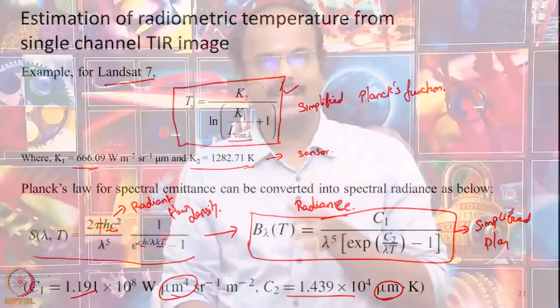So, once we have such an equation, if we substitute the corrected radiance, we will get this. This method we have seen is known as retrieval of LST using the radiative transfer equation. We took the basic equation, looked at which components are present in the atmosphere, and tried to estimate them separately. Given current circumstances, even without access to any sophisticated models, we will be able to retrieve land surface temperature using this method, because the atmospheric correction tool is available to us. Emissivity we can simply calculate using NDVI, a very simple method I have explained, and substituting in this equation we can do this. But this is not the only way to retrieve land surface temperature.